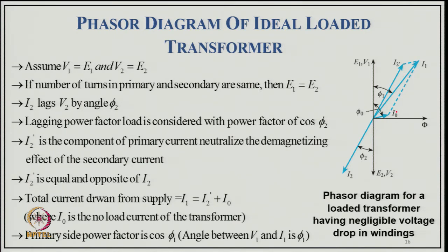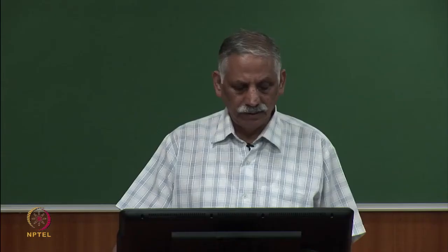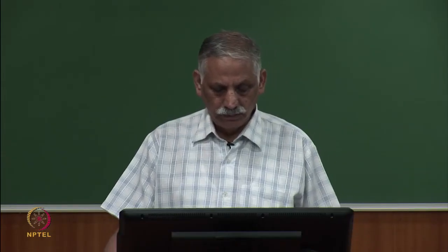So, these are typically the phasor diagrams of a loaded transformer with an ideal transformer, where we are neglecting, of course, the resistances of the windings as well as the leakage reactances of the windings. So, now coming to discuss useful and leakage flux in the transformer.